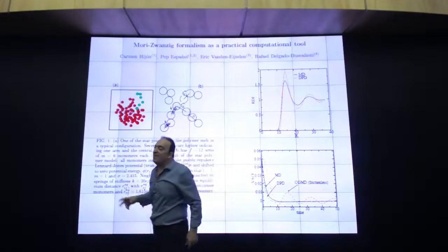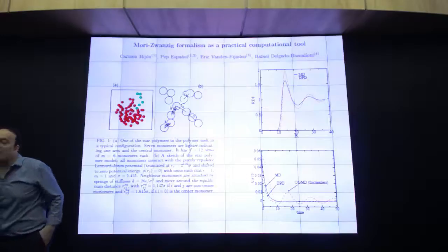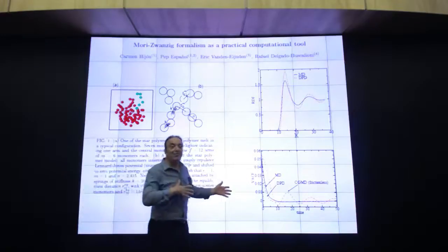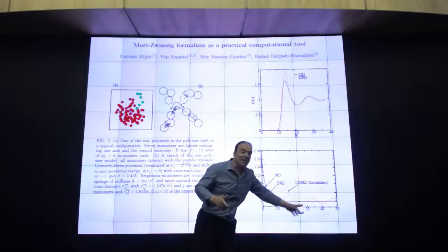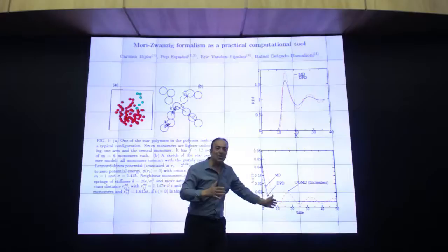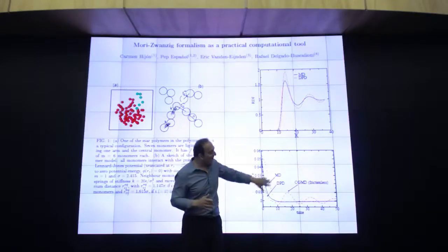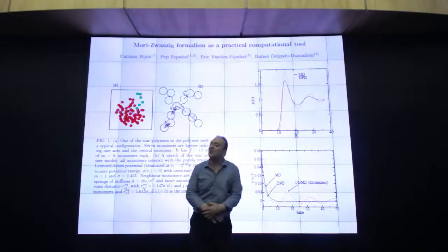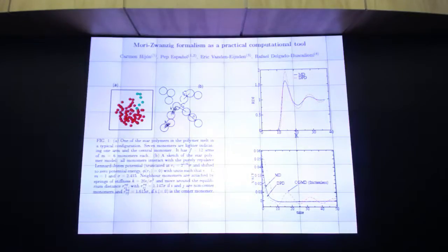Now, if you integrate that for diffusivity, you get lucky. See how lucky you get, because the integral of that gives you the diffusivity. This cancels with that, almost, this cancels with that. And within engineering accuracy, the naked eye would say, okay, this is pretty good. It works. So if you ask your colleagues, they say it works. Well, it doesn't work, because the velocity correlation function is totally wrong. Some sort of averaging of that, with the right circumstances, all planets aligned, will give you the result, but it's wrong.